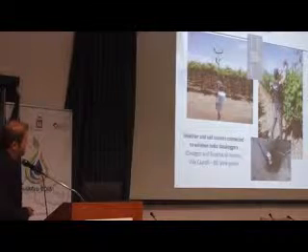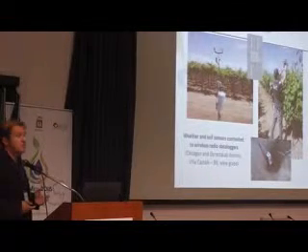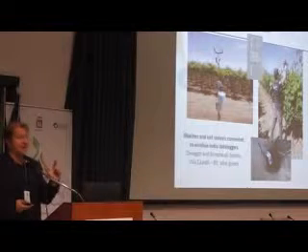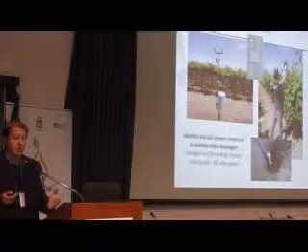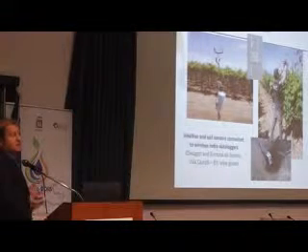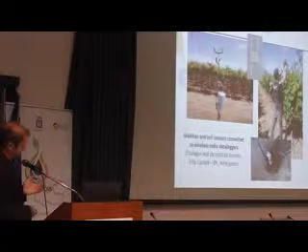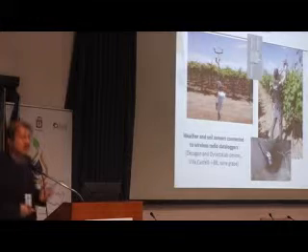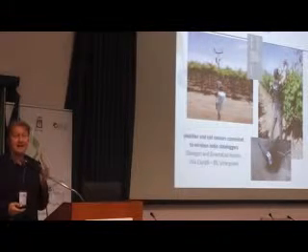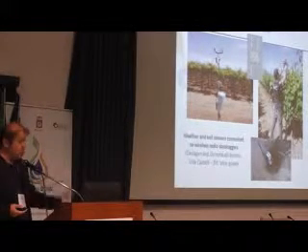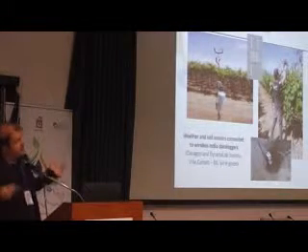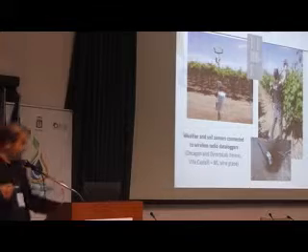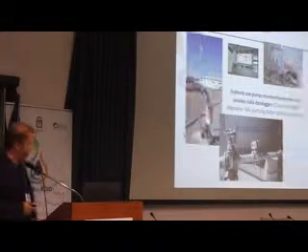In the case of soil, you see we try to put sensors at 2 depths in order to understand if we are giving more water or less water than necessary. But there are a lot of problems, because it is very difficult to have really good measurements of soil moisture. It has been a problem for many years, and this is something that will remain a problem in the future.